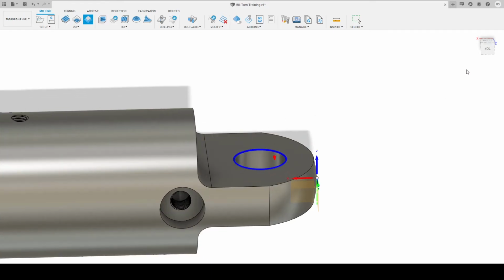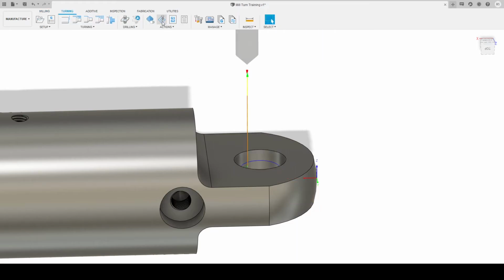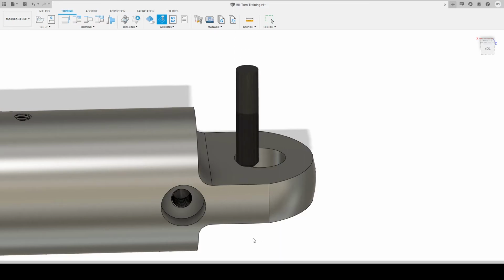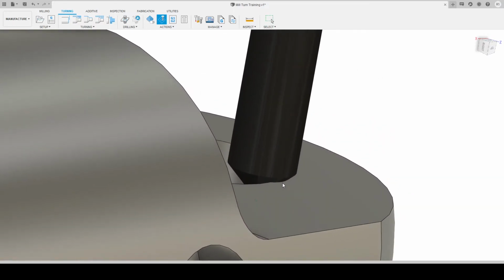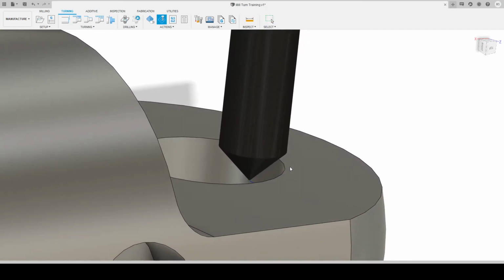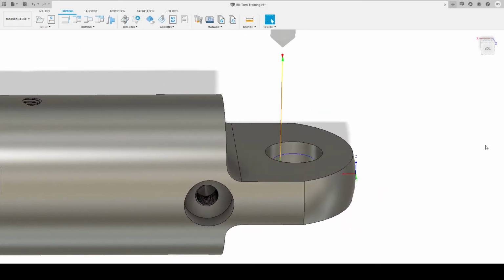and then it will actually show you selection properly. Okay, under passes, so now we can sort of use the chamfer width. So if we go 1 millimeters and 3 millimeters, it'll go in 1 millimeter and then drop down 3 millimeters and do a chamfer. We will simulate that. So you can see that it is actually cutting a chamfer now, and it's offset the tip down. Hopefully that makes some sense to you.